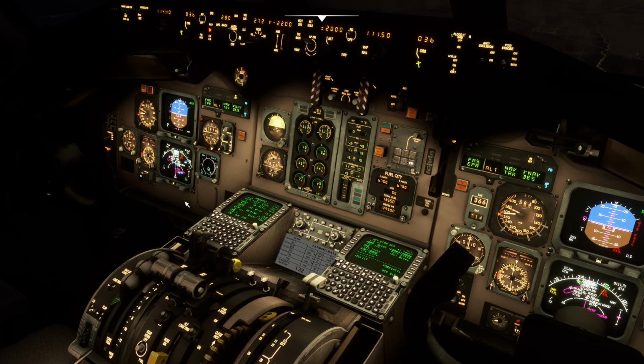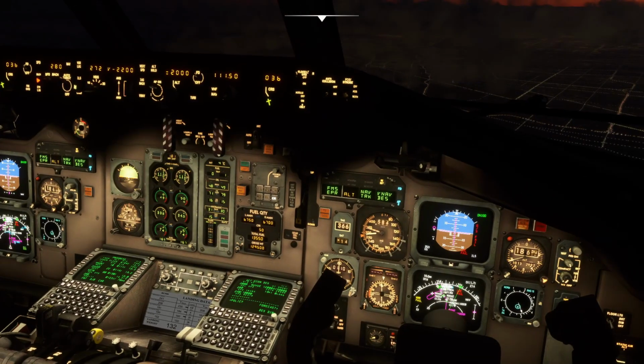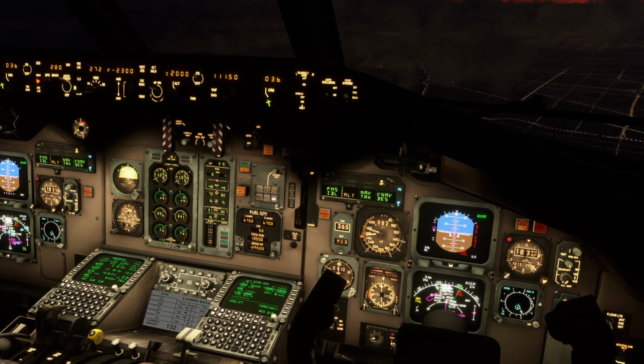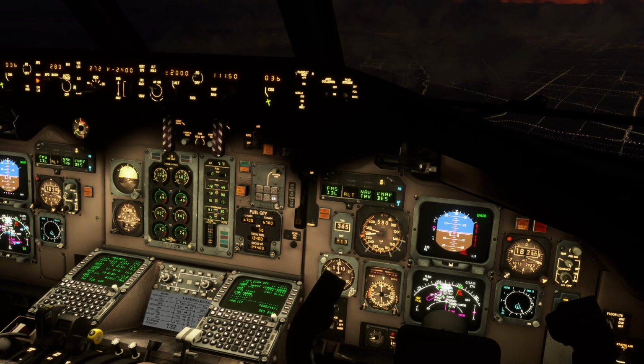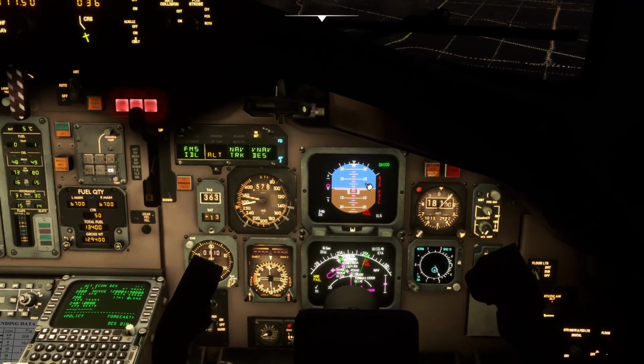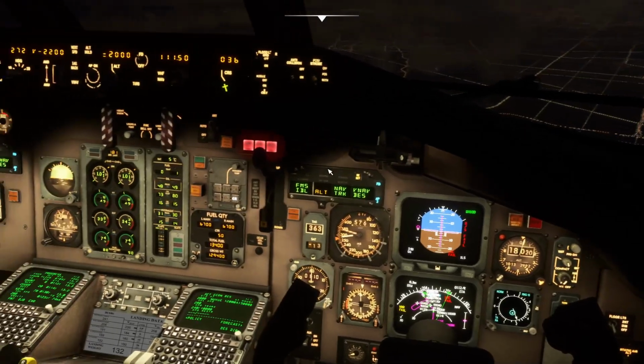Alright, just to give you a status update. Cleveland Center's come online, and we've got 8ish for Detroit Metro, so we're going to switch to the 3 right approach, ILS. So I've updated for that, so it's new frequency, new minimums. I'm not going to bother recalculating because it's basically the same runway.